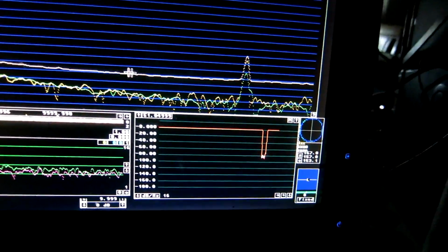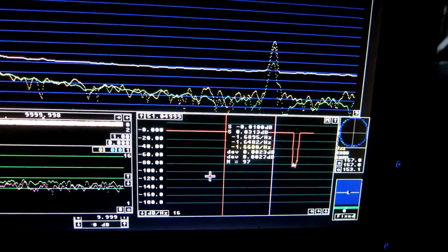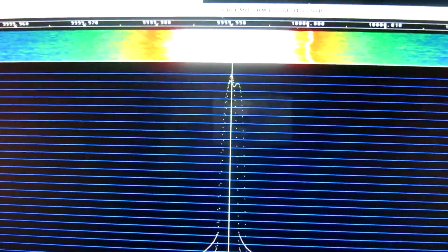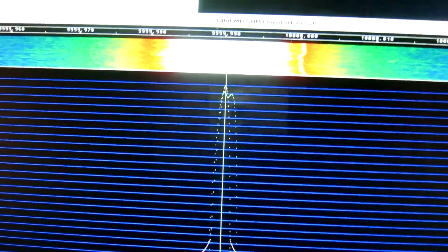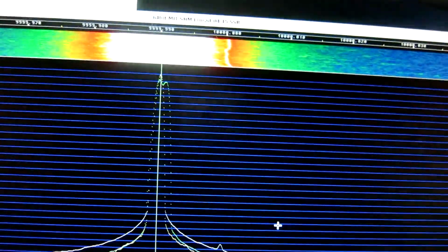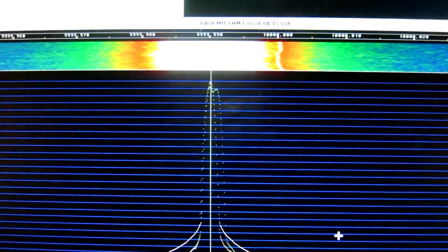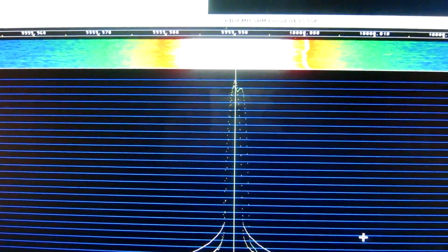The level I see here is properly set, it's 0. I had to decrease the attenuation after this selective amplifier, or rather oscillator, to make this collection of data happen at the same signal level into my analyzing circuitry, the dual channel direct conversion receiver.